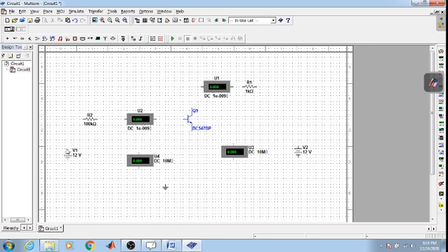We connect the positive of this to the resistance here. For the resistance, you just need to single click and select the point, and drag and drop and click at the other point. When you place the cursor at this location, it shows a circle, then click over there and drag by keeping your left mouse button clicked, and leave at the position where it shows there is a connection and click over there.